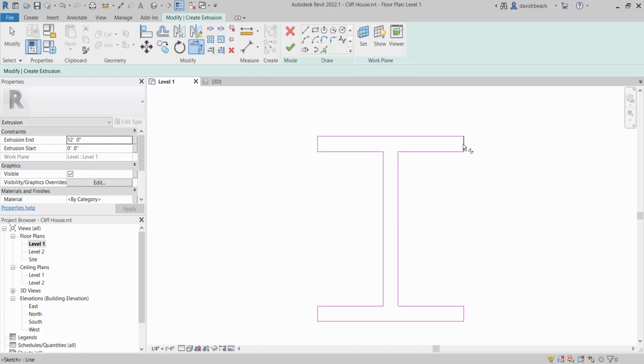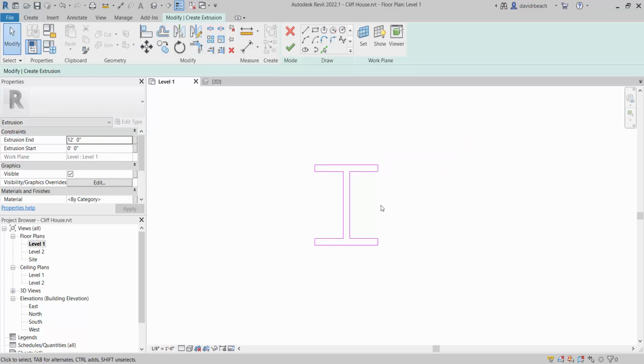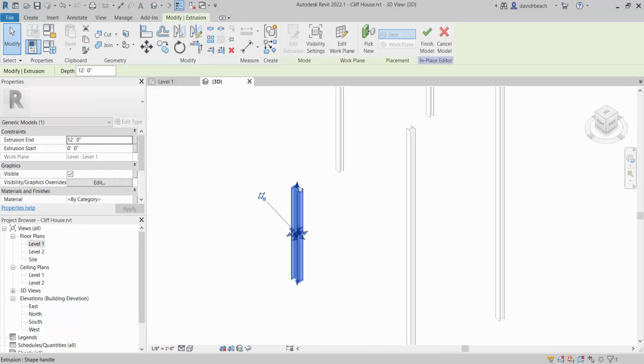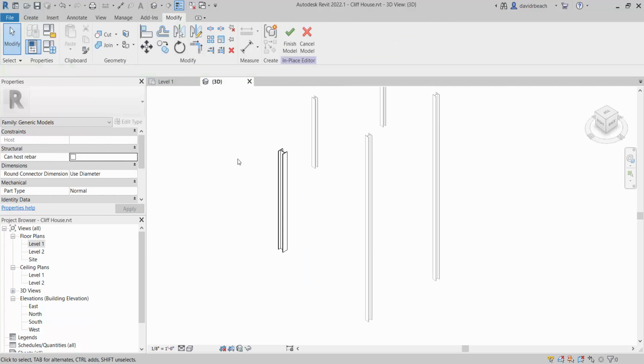And again, this isn't the way you'll always do I-beams or W sections in the future, because there are preloaded ones, but for right now, as you're learning this content, this is how I want you modeling them. Okay, I don't want you using the button to bring in an I-beam. You'll have more design control over this as a system than the pre-built structural components. So this is how I want you modeling this content, right? Pretty easy and pretty fast to do, especially when you're working on a project and you're going to have multiples of those to push and move around, right?